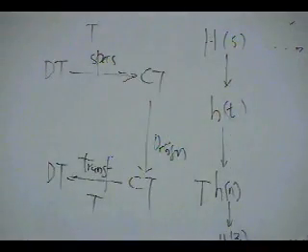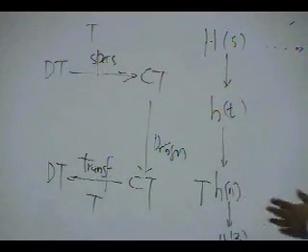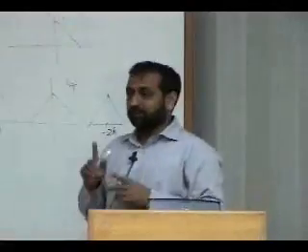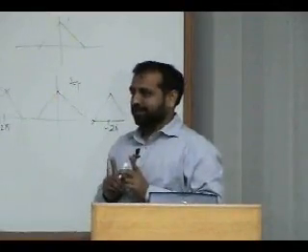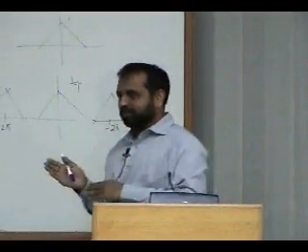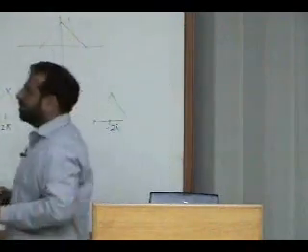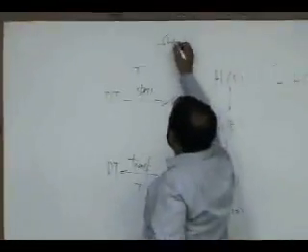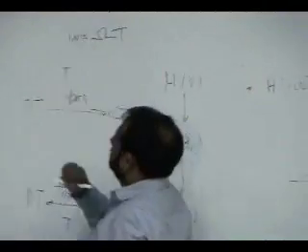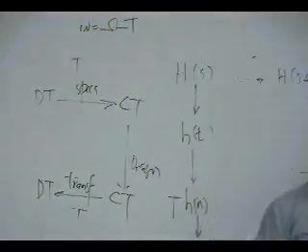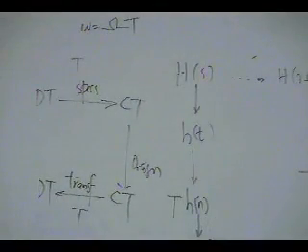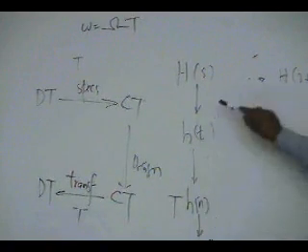So if I'm going from discrete to continuous and continuous to discrete, the T will not matter. But the important point is that you need to make sure you keep the same T. Once you convert these specifications from small omega to capital omega, using capital omega T equal to small omega, the same T should be used once you discretize this expression. And we'll see how to do this.